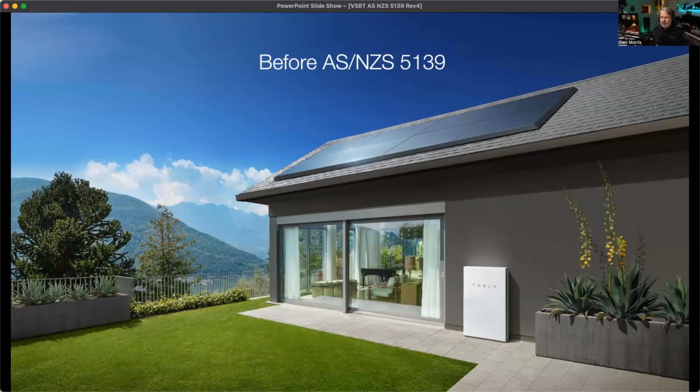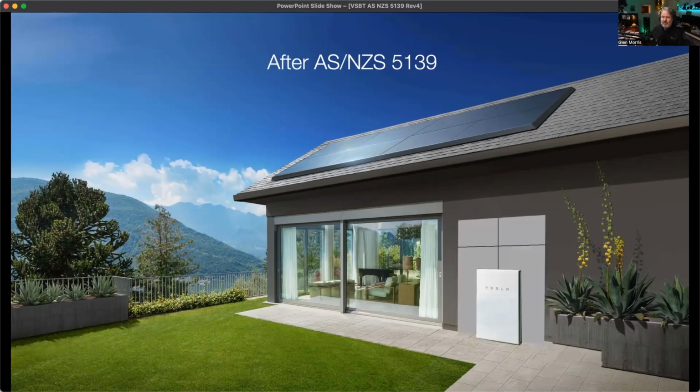If that wall wasn't one of the fire-rated materials like brick, concrete, terracotta tile, or cement sheet, which I'm assuming is a structural insulated panel, SIP, I'd have to put up a fire barrier behind it. That's typically cement sheeting or one of the other fire-rated materials listed in the standard.